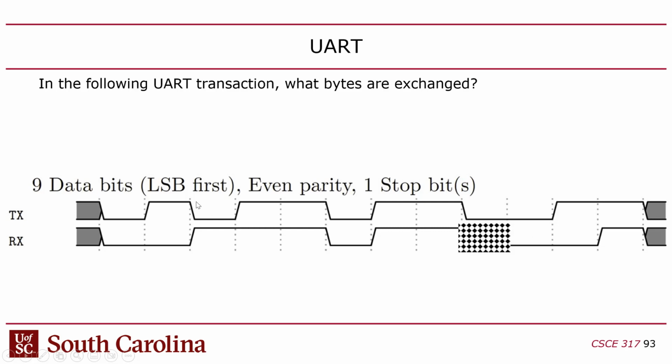The total number of 1 bits there is 1, 2, 3, 4, 5, 6. Again, we're not counting the stop bit, and we're not counting the start bit. But in the data and the parity bit, there are 6 1 bits, and 6 is an even number. So according to the parity check, there's no error in this channel. Of course, there could be 2-bit errors; if we flip 2 bits in the channel, we wouldn't detect that. We would only detect a problem if there's 1 bit error.